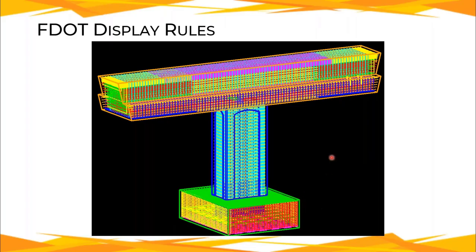And when I do that, I can get something that's much more clear, much more easily digestible, especially when you're working with rebar and congested caps and congested areas. You get so many lines that represent the edges of the bars, and you can really get lost in there at times. So using a display rule, I said, okay, go ahead and change cap 1 level to blue, cap 2 level to pink, cap 3 level to purple, and then it's a lot easier to see what you've got going on in a rebar model here.